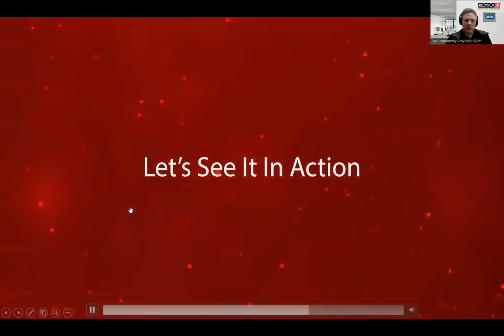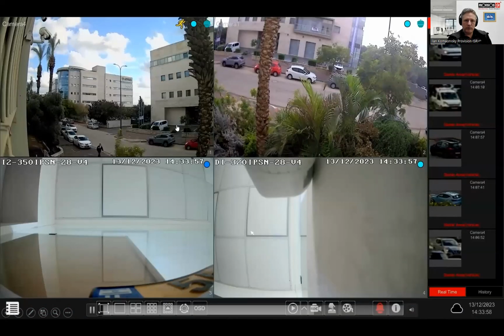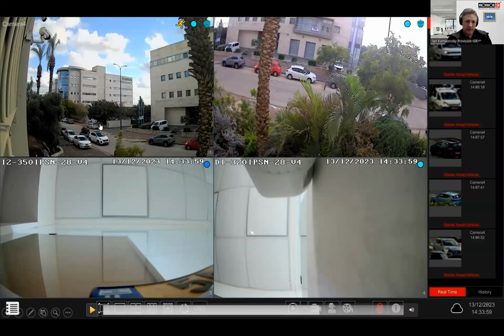Now, once we see that there is a motion, you see it's now divided by 4. When the DVR detects that there is a motion, it's going to check inside this motion. If it's highlighted by those green squares, and we find that there is a target, which is humans, then we're going to see a full window pop-up. So we'll know that this process is actually working.